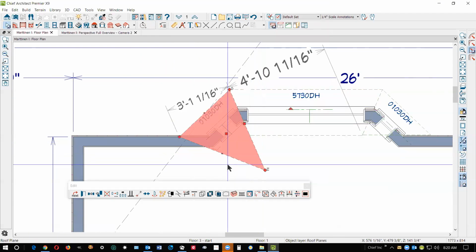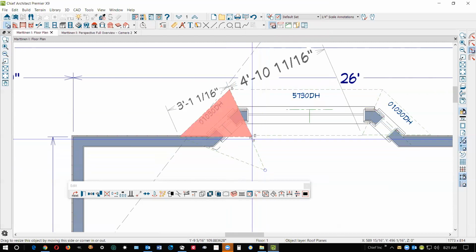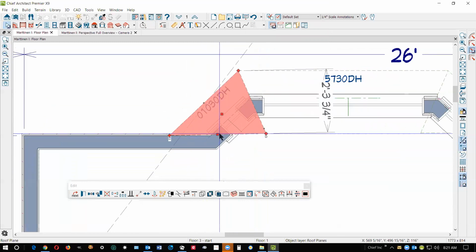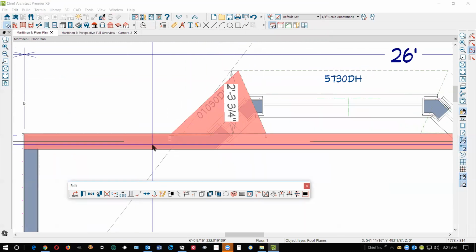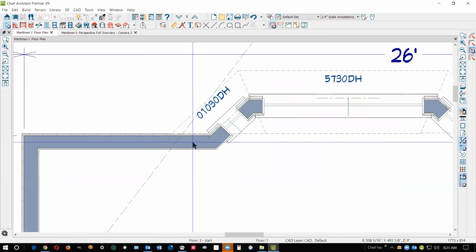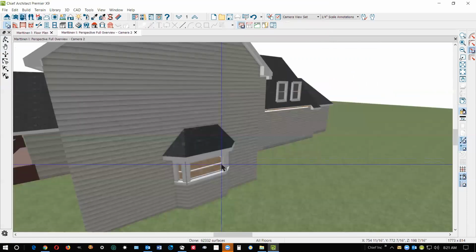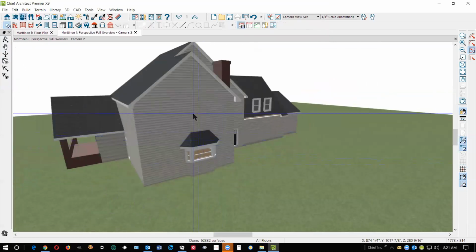Yeah, it worked, except for this line here, it didn't parallel up. That's okay. It's not supposed to automatically do that. And then take this and parallel it. When you're manually editing roofs, you have to just assume that everything's not parallel or perpendicular, and after you make a move, you make sure that they are, so you know it's cleaned up.